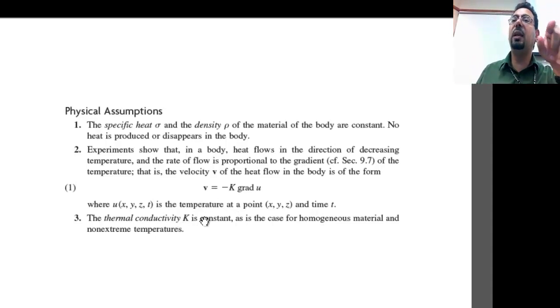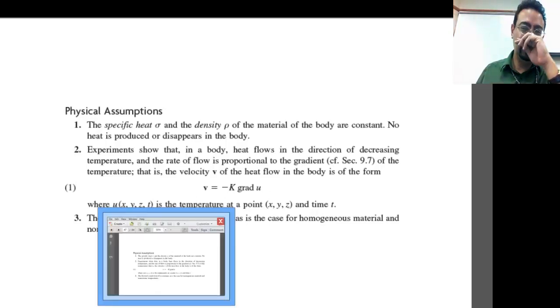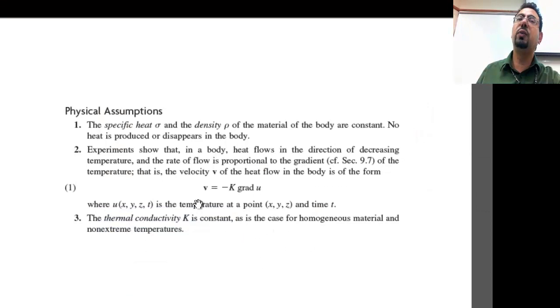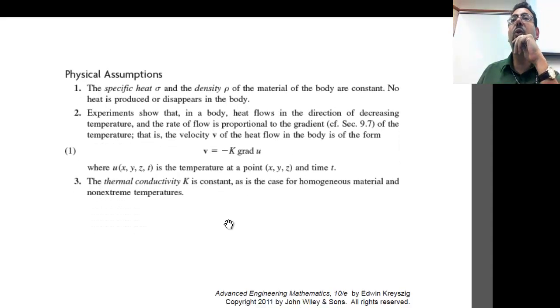In heat transfer, the flow of heat should scale with the temperature gradient times a constant. Of course, in heat transfer in this school, for the heat flow we use Q, and for temperature we say T. It's partial T partial X. Fortunately we also use K, so it's the same conductivity. So the Fourier law is Q equals minus K partial T partial X. He's saying that the conductivity will control the heat flow.